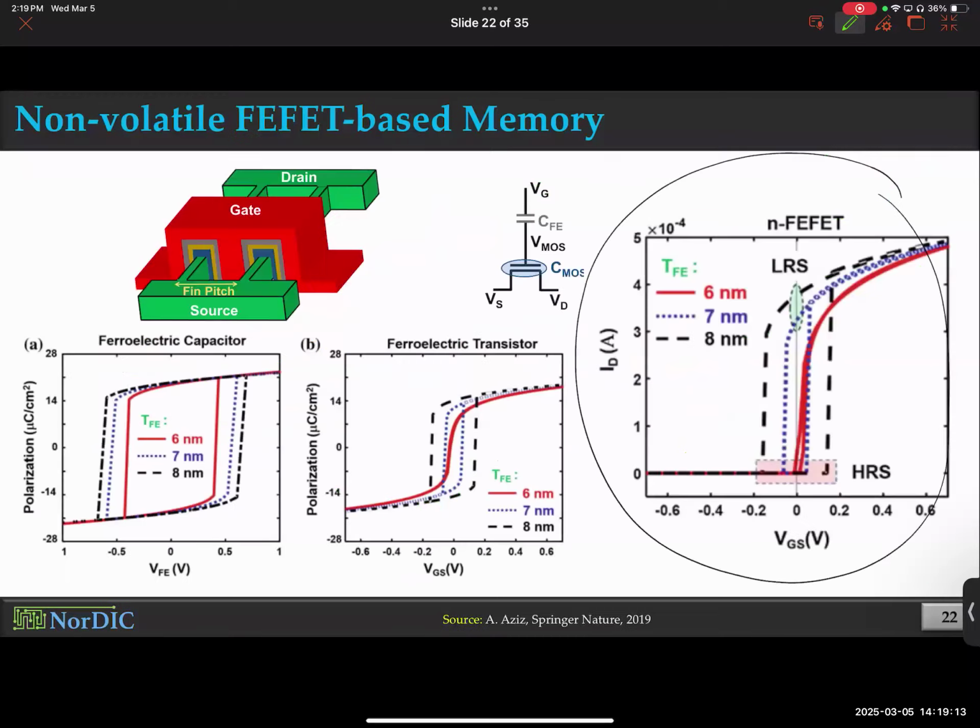All right, so getting back to this point, there are many good things about FeFET-based memory: separate read-write path, and especially if you are going for hafnium zirconium oxide-based FeFET, super simple fabrication. You don't have to change your tools. That was the deal maker for industries. We don't have to buy new tools. It's kind of like having the same coffee maker, but using it to make other drinks as well, right? You can make Coca-Cola with my coffee maker. Sure. Okay, I'll take it.